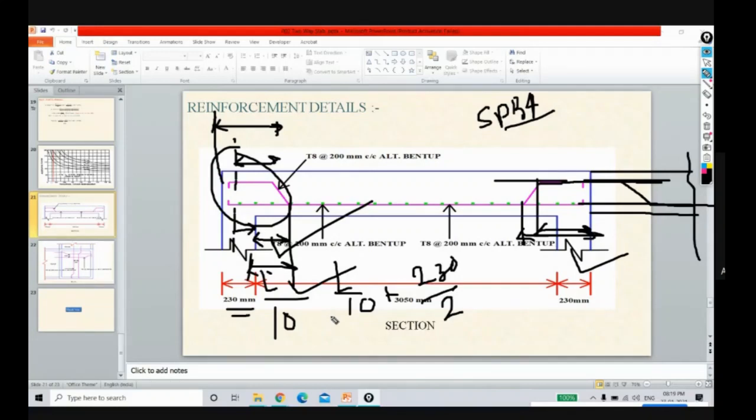Sir, one question. When we detail slabs where there are different panels in continuity with different sizes, and the support negative steel at the supports is different for both the slabs, what is the ideal way of detailing those bars? Alternate bars, or providing an extra bar where there is less steel? What is the way to do that, while providing the reinforcement?